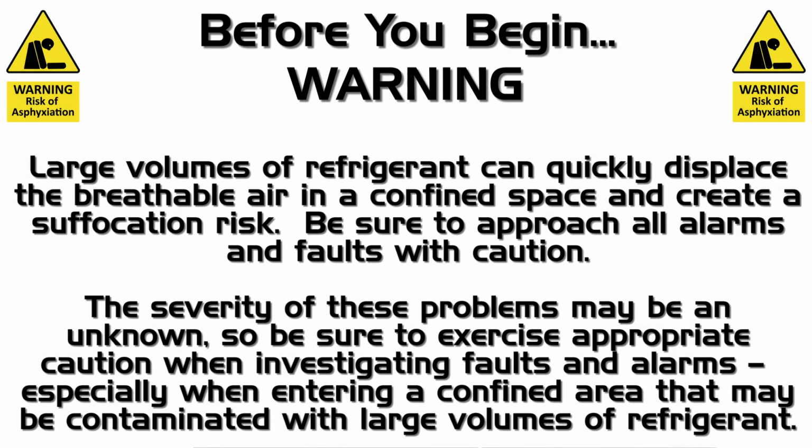Large volumes of refrigerant can quickly displace the breathable air in a confined space and create a suffocation risk. Be sure to approach all alarms and faults with caution. The severity of these problems may be an unknown, so be sure to exercise appropriate caution when investigating faults and alarms, especially when entering a confined area that may be contaminated with large volumes of refrigerant.